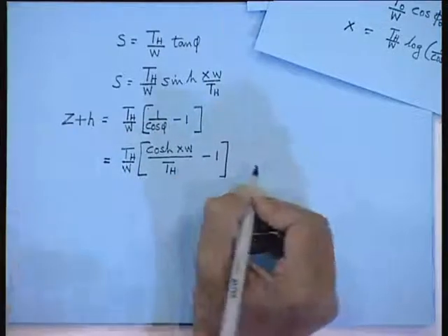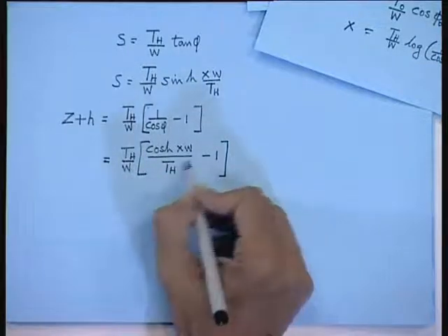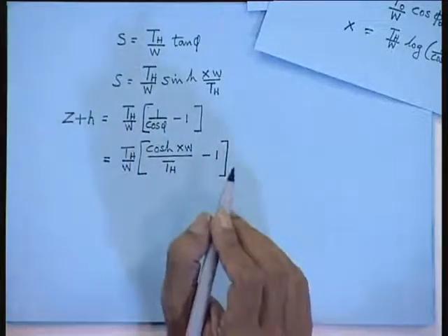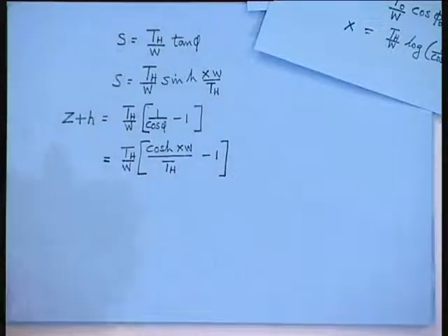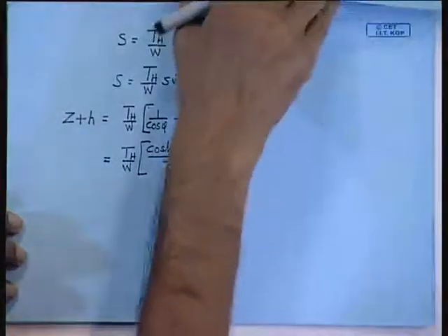So here, what are the unknown parameters? So again TH, W you know. x is the unknown term, h you already know. So from this you can find out z. Now, the other thing that is remaining is line tension T, which is our primary focus. You calculate line tension T.